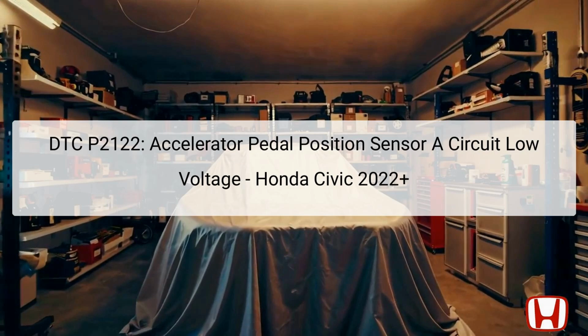The APP sensor, integrated with the accelerator pedal module, plays a crucial role in translating the driver's acceleration input into electronic signals that the PCM can interpret. When the output voltage from the APP sensor falls below the specified threshold, the PCM identifies an abnormality, thereby storing this fault code. Components affected include the APP sensor and associated electrical circuits leading to the PCM.